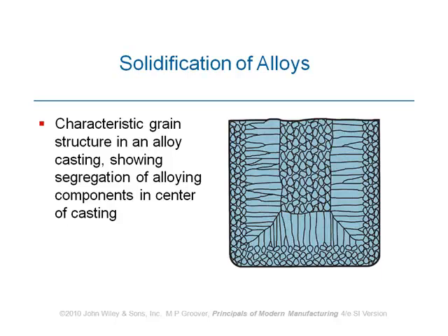Okay? So what we get is that the surface, some small grains on the surface, which is component A, for example, with a higher melting point, and those sitting at the core are the ones which are richer in the other component. And the melting point is lower, of course. And that's the last point, position or section of the material to solidify.